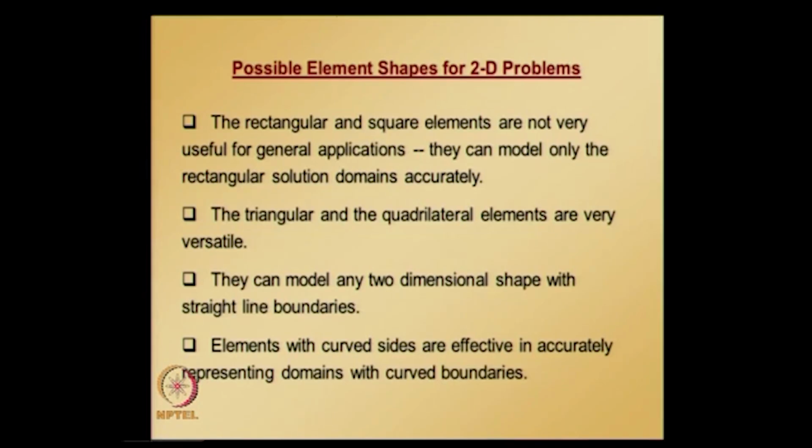As a part of this lecture, we will be looking at the equivalent functional for the 2 dimensional boundary value problem statement that we looked at, and the equivalent functional is required if the finite element solution is based on the Rayleigh-Ritz method. And we also look at how to derive element shape functions for the 3-node triangular element. The procedure helps us to generalize it later for any noded 2D element.